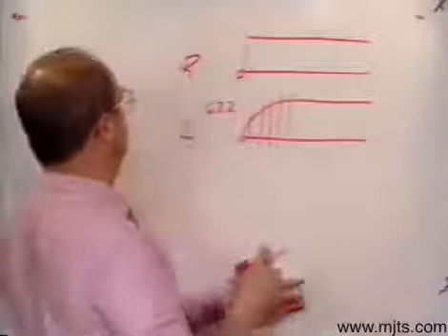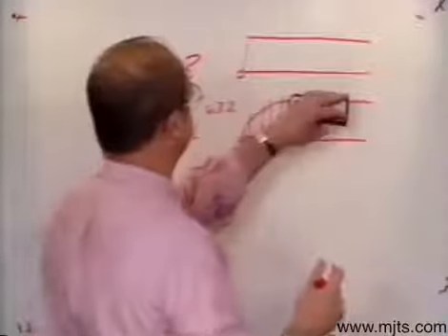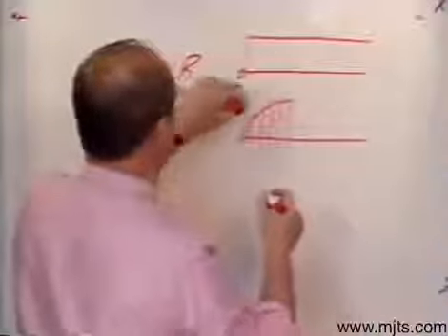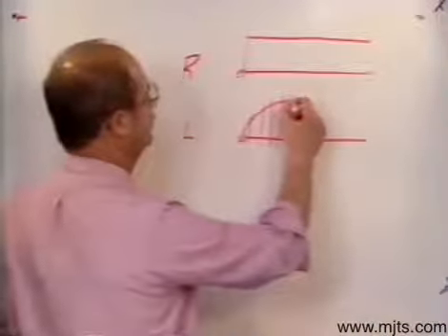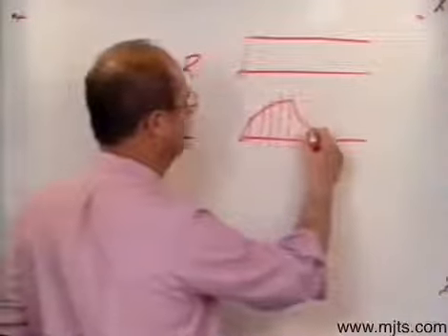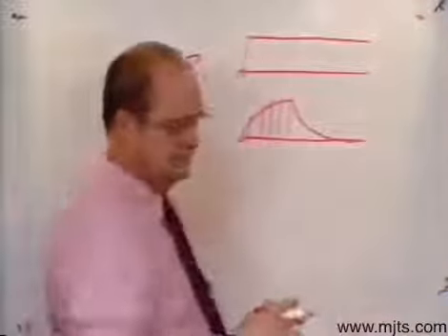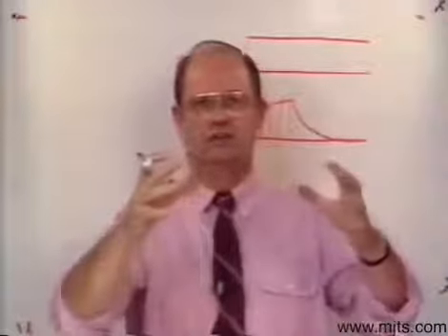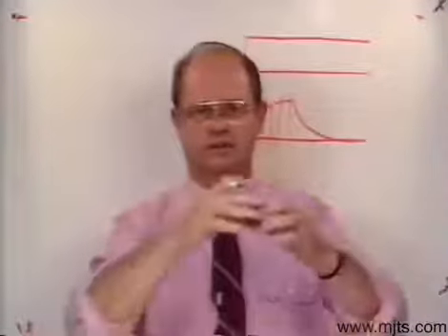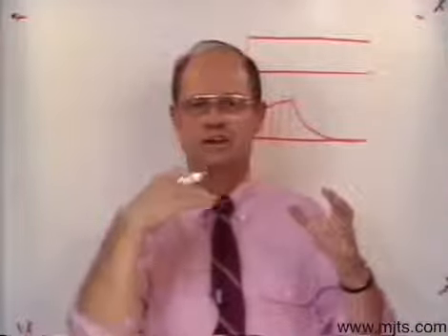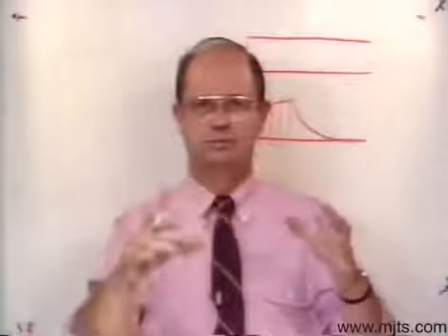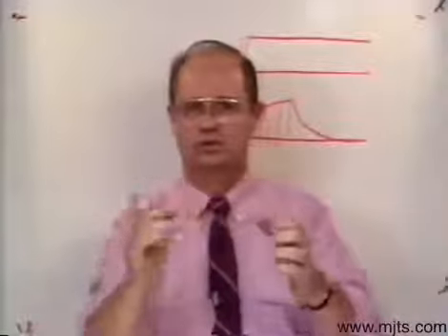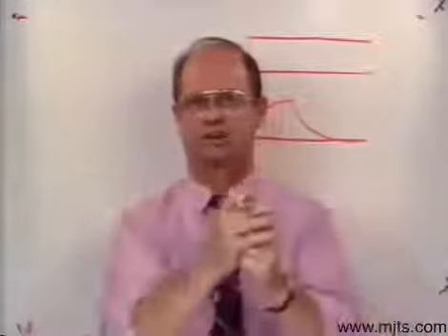If I were to de-energize that circuit after it reaches its maximum, it'll go through the reverse procedure, only this time it'll go through time constants to decay down to 0 again. Now they call this stored energy. Once the magnetic field around the wire, or the coil in this case, is built up, and you de-energize it, or you shut it off, you open the switch, it'll collapse down around. In other words, when I open the circuit, the magnetic field collapses, so it's like stored energy.